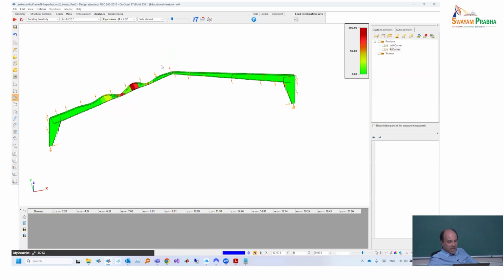So we have this deformation as a buckling mode, we multiply it by 1 millimeter, we change it into a deformation, and for each of the finite elements we calculate the associated deformation energy. We don't know exactly how many joules it is, but it doesn't matter, because we don't know the scaling. That's not relevant, it's not the real physical value.